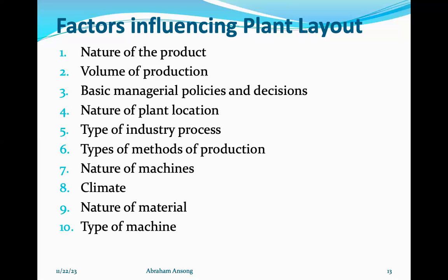And therefore, more attention can be paid to machine location and handling of materials. So if you're dealing with heavy products, you need to use what is known as stationary layout. But if you're dealing with light products, then you may have to consider line layout. Stationary layout and line layout are very important, because with one, you don't have to move from one place to the other.